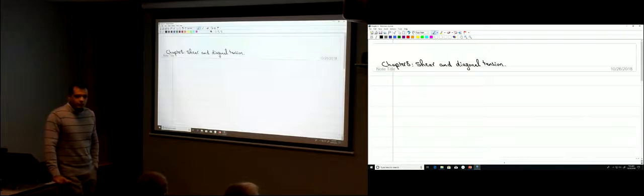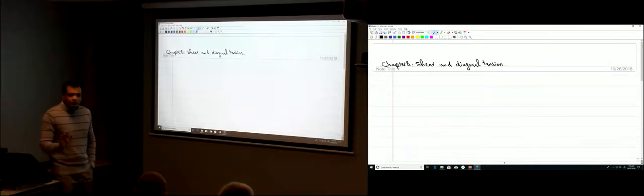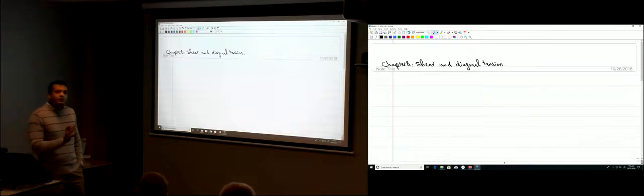So actually you have a bending moment. We said there can be three internal forces at a section. What are those three internal forces that can occur at a section? Normal force, shear force, and bending moment. So right now all we did is a design for that bending moment. We still need to learn our design for a normal force and for the shear force.